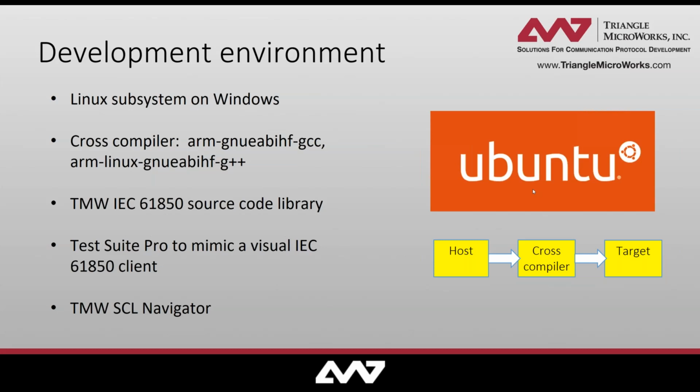And we will be using the TNW's IEC 61850 source code library for this application. And we will also use the TestSuite Pro, which will be used to simulate the IEC 61850 client or the distribution system operator. And then we will also use the SCL Navigator in order to edit the ICD file in order to create a mapping between the server and the ICD files.